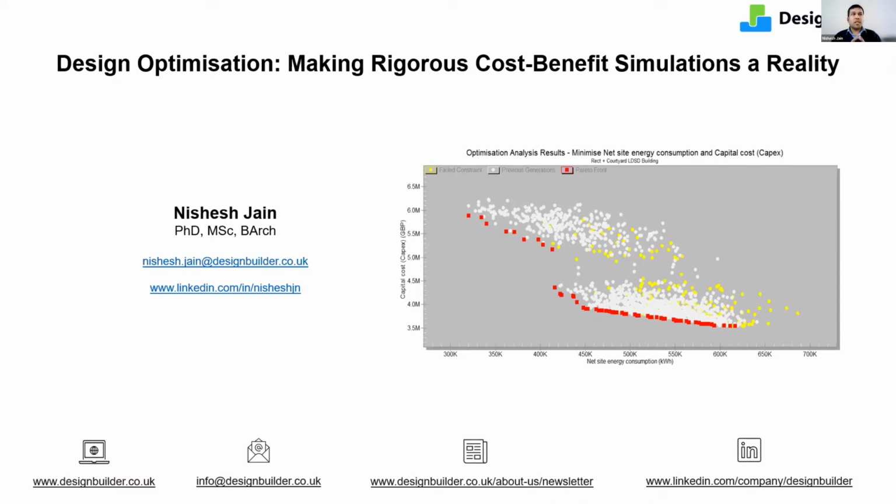So it was there, but my suggestion would be, if you are doing a complicated, complex optimization problem, don't bang in every possible permutation and combination. Actually, you should try to make some intelligent optimization choices by eliminating the obvious variables and minimizing your search space as much as possible. Using sensitivity analysis of your model as a precursor to optimization can really help you make the process more efficient.